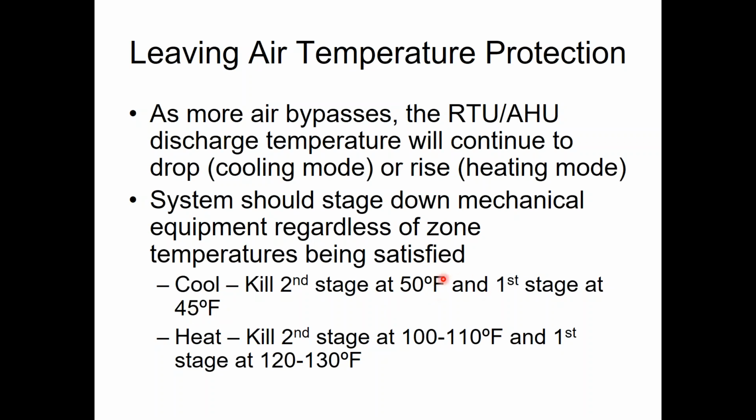Once again, remember, I don't have any control of discharge air. Whatever happens, happens. So if only one or two small zones are calling for cooling and I have a stage of cooling on, it's very plausible that I'll get down below 45 degrees on the discharge air, and I'm going to have to kill that thing and stop it until such time as it warms back up, and then I can let it run again. So we're going to put those safeties in for sure.